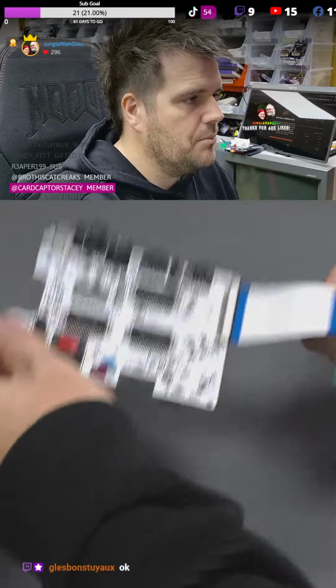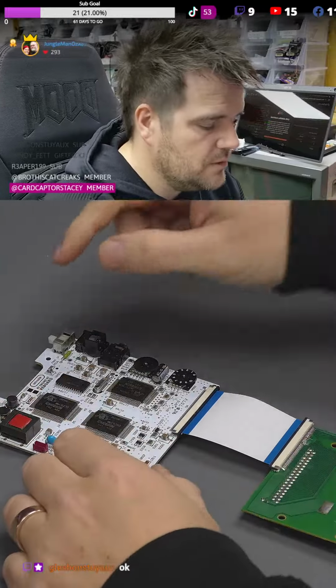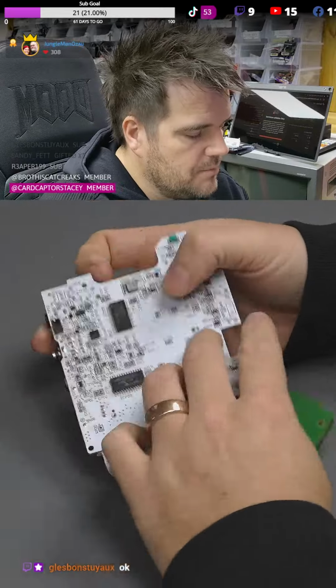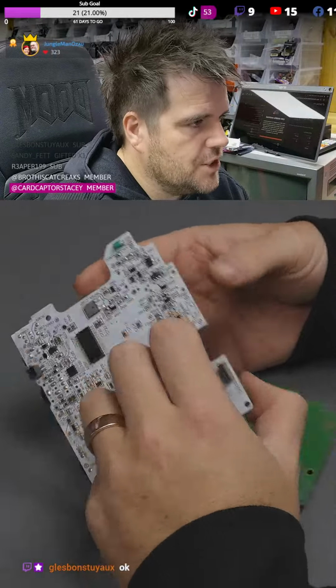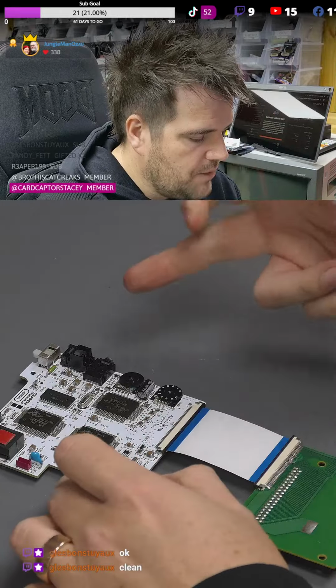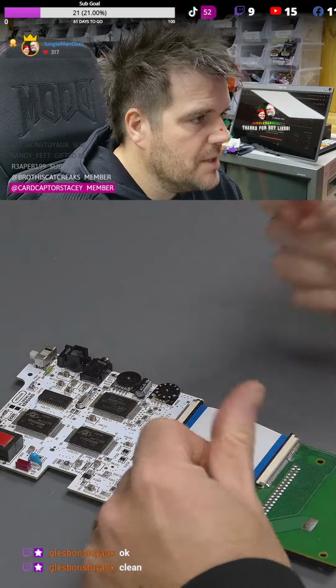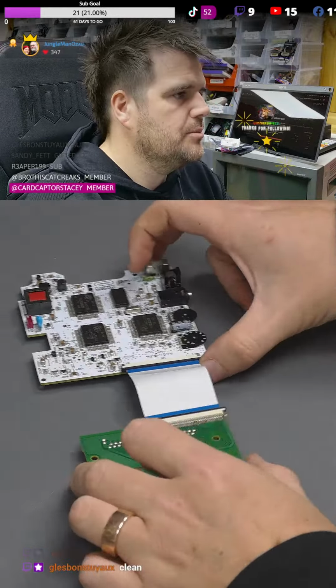I'll bring this up later on stream. We'll have to apply power slowly and make sure the regulation circuit works and we don't overvolt, because this is obviously the first check. If we then get 5 volts, we can put a game in, probably put headphones in and listen for game audio maybe. But I'll try and bring this up later.